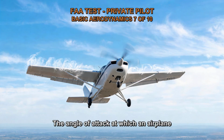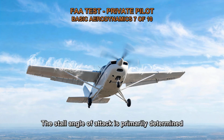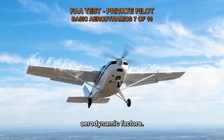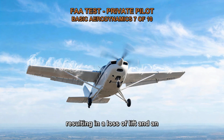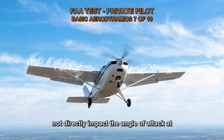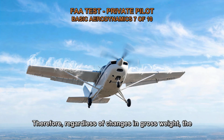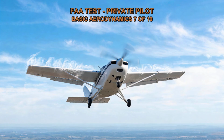The angle of attack at which an airplane wing stalls will remain the same regardless of gross weight. The stall angle of attack is primarily determined by the wing design, airfoil shape, and other aerodynamic factors. It is the critical angle of attack beyond which the airflow over the wing becomes turbulent, resulting in a loss of lift and an aerodynamic stall. Gross weight affects the overall performance of the aircraft, including its stall speed, but it does not directly impact the angle of attack at which the wing stalls. Therefore, regardless of changes in gross weight, the angle of attack at which the wing stalls will remain constant.